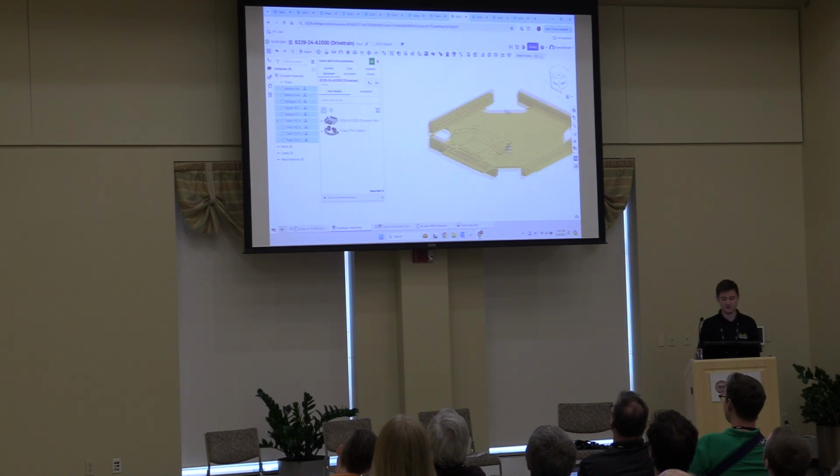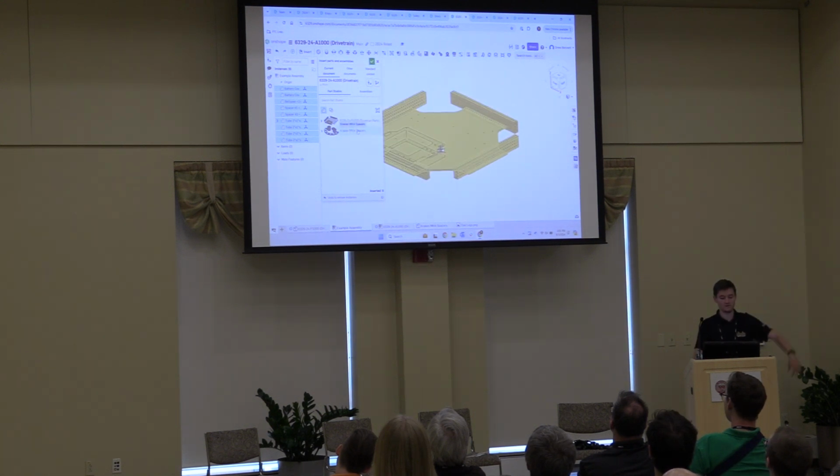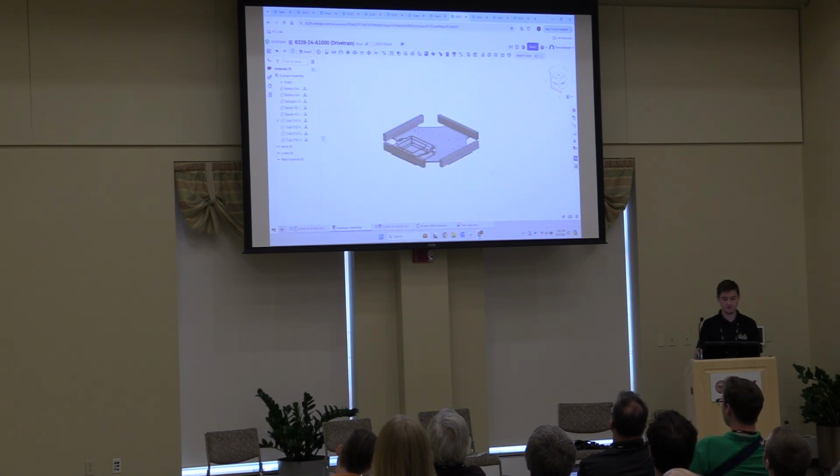Of course, if I go into space, I can see it's moving around. If I stay over the menu, it's going to drop directly on the origin where it's modeled in the Part Studio. So just click on it, click check, and pretty much all you need to do is select it all and group it. That's it. Now all the parts are stuck together.